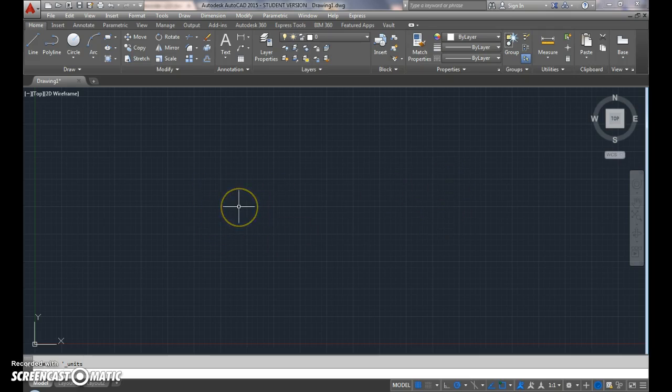I normally start a floor plan on the lower left-hand corner. That's kind of my benchmark place to start and go from there. You certainly don't have to, but you definitely want to start by boxing everything in. Whenever we draw a house on our floor plan, you're going to draw walls on all the outsides, and we're drawing basically the exterior lengths of walls.